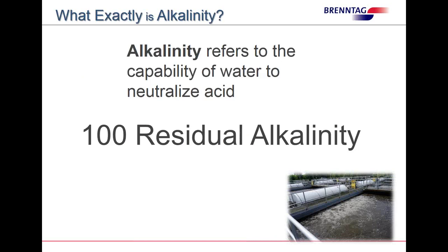Okay, alkalinity. Alkalinity refers to the capability of water to neutralize acids. What I like to say in my talks is, let's try to strive for 100 residual alkalinity. The reason I want 100 is because I want to make sure that we have enough there. Now, if you want to get real down and dirty about alkalinity, it's like a floor that holds the pH up. So if you break through the floor, you're probably going to get a very, very low pH.